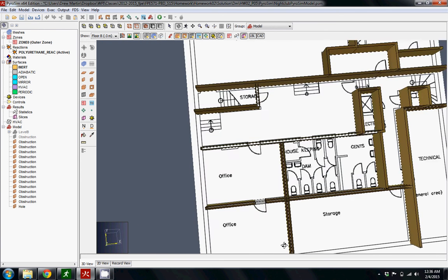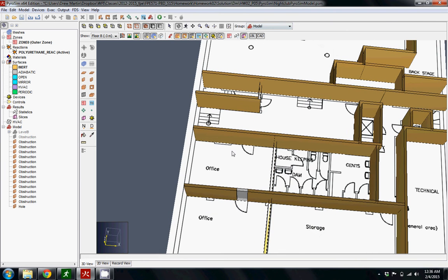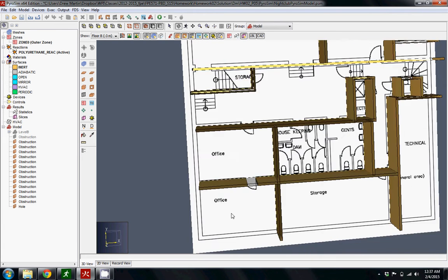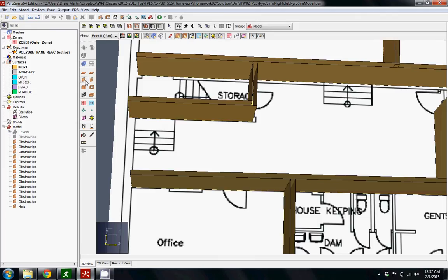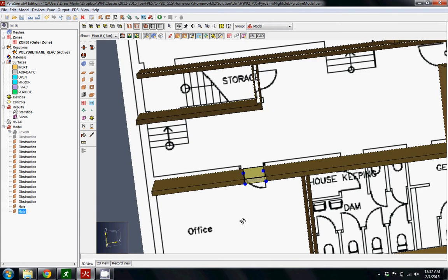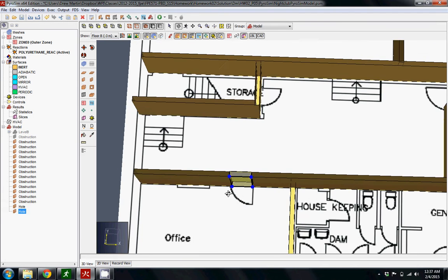And that'll just make sure that it's on the right elevation. But now we're going to be using our trick that we learned so that we draw it on the correct side of the wall. So again, if we're using the wall tool like this, we want to draw it on this side because it will go into the wall. So there, we drew it perfectly. We don't need to move or change it at this point.